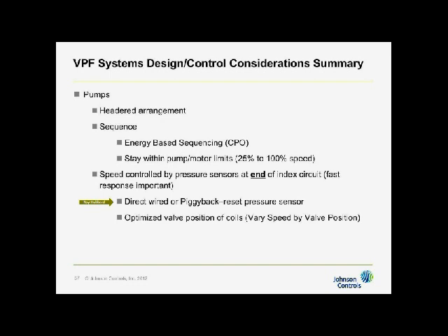That one in the plant is actually controlling the variable speed drive. So you get that direct, fast-acting control, so you don't hunt, but it is controlled through the network by the pressure sensors at the end. Now it'll work. It's called piggybacking. So the pressure sensors at the end are constantly resetting the pressure in the plant that controls the variable speed drives.